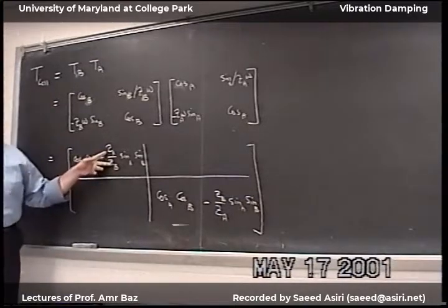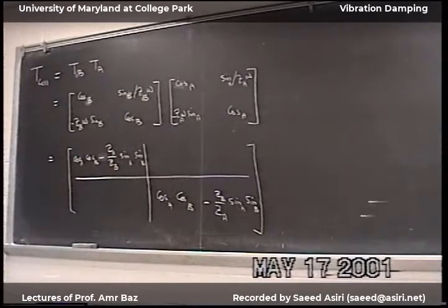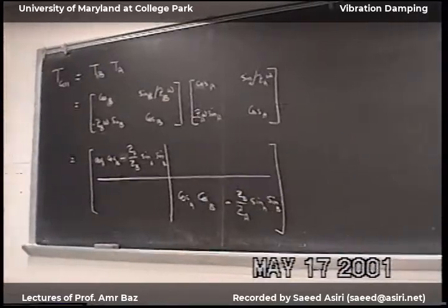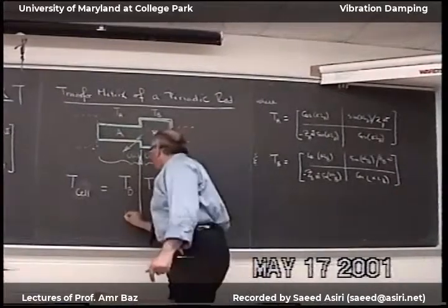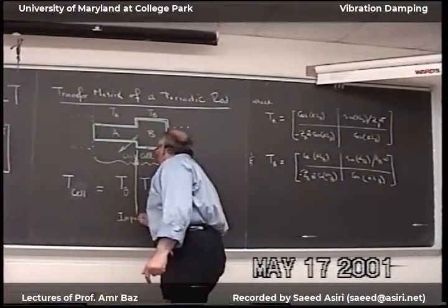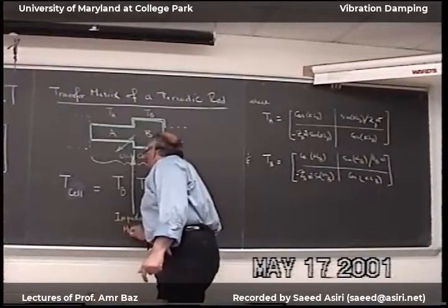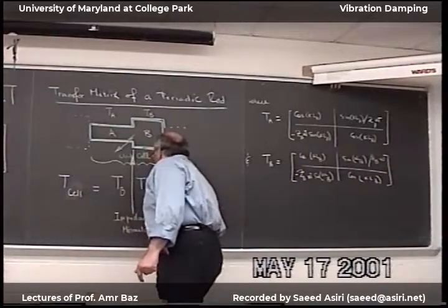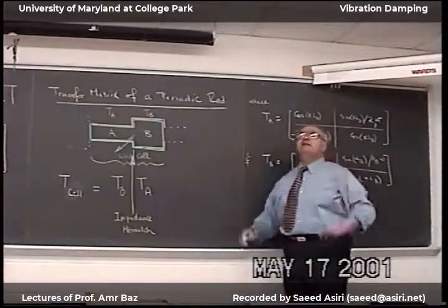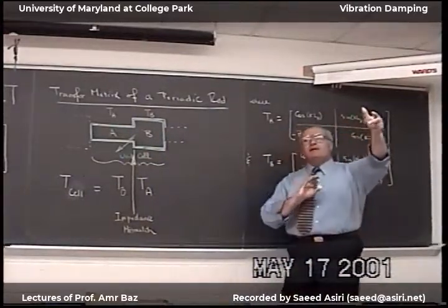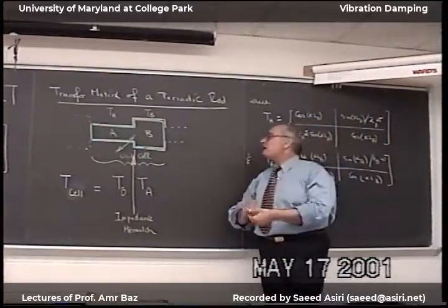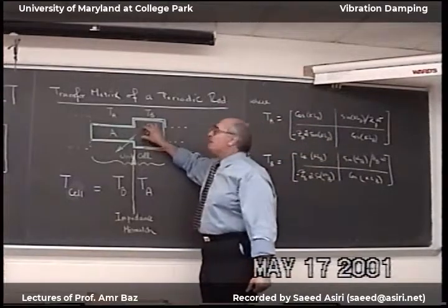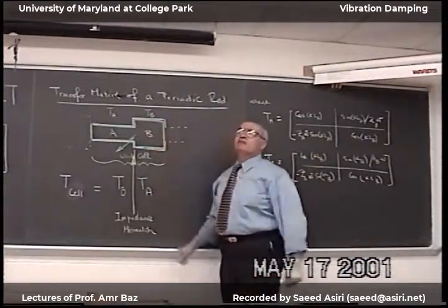If there is impedance mismatch at this interface, this ZA is different than ZB. So at this level we have impedance mismatch. Then our eigenvalues can be as we want, either real or imaginary or combination, so we can have stop band and pass band. And then, if I make this a shunted piezo, then I can do a lot of things on it.